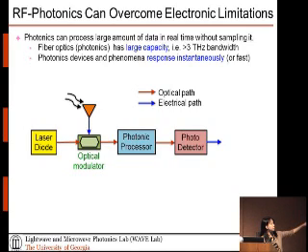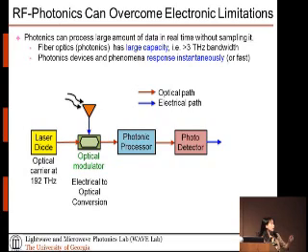So first, we have a laser diode shown on the left, an optical modulator, a photonic processor, and a photodetector. So what does the laser diode do? Basically, it acts as an optical carrier at 192 terahertz frequency. At the optical modulator, we do an electrical to optical conversion by using the received signal to intensity modulate the amplitude of the optical carrier, so that the copy of the electrical signal becomes an optical signal. So we can process it all optically in this optical processor.